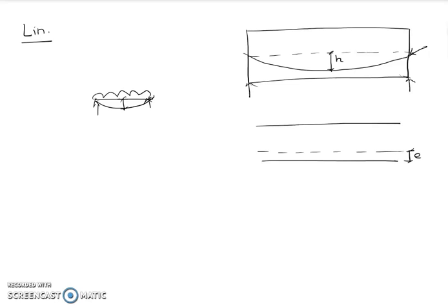We know that the deflection is going to be like this for this particular beam. That is the reason we provide the tendon in such a way that maximum sagging happens in the midspan. So the tendon is provided in a parabolic manner with the maximum vertical distance at the center as H and it is 0 at the ends.